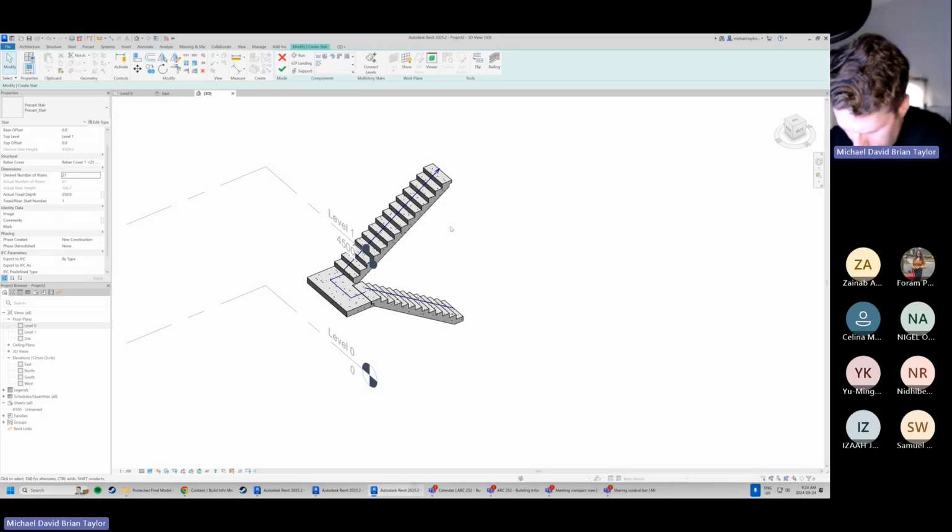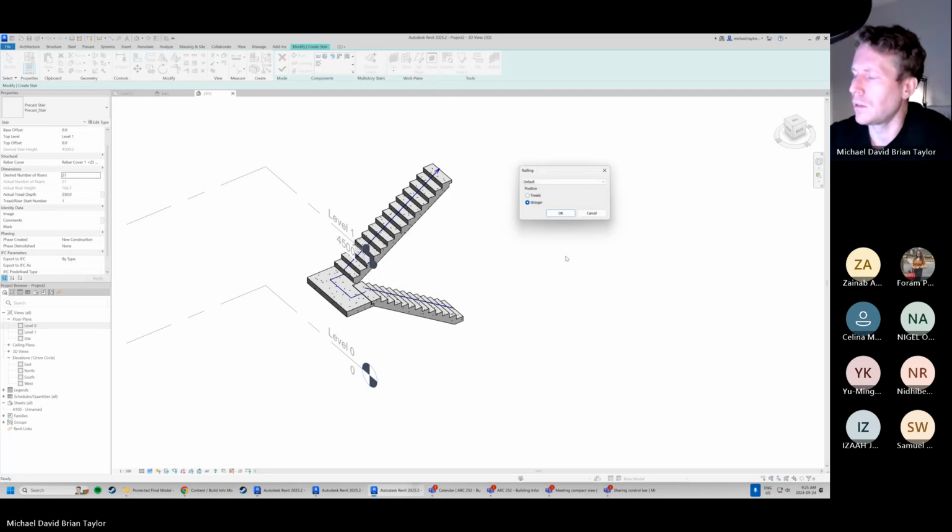One of the other tools here is the railing. The railing can also be part of the stair. So if we come back in here and click this little railing tool, we've got a couple different options. The railing is, of course, the guide as we get down the stairs. Because it is all automated, it can be really helpful for us to either set it now or modify it later. And this is setting up the railing itself.